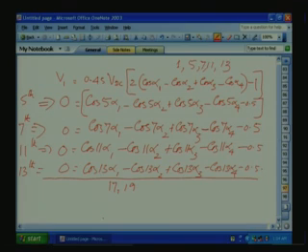But in the context of multi-level inverters, people are still coming up with PWM techniques based on these harmonic elimination schemes. But we will not come to that now. What we want to remember here is that to suppress the low order harmonics, we have to introduce notches with the proper symmetry, then write down the Fourier series, and for the harmonics to eliminate along with the required fundamental, we have to write these equations and solve them.